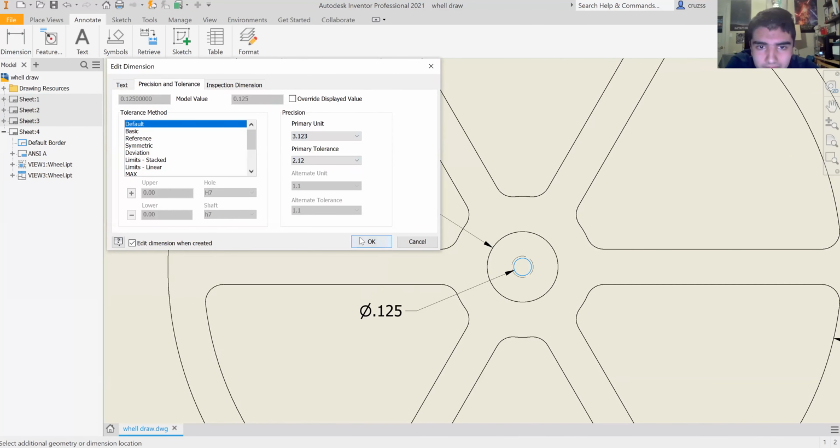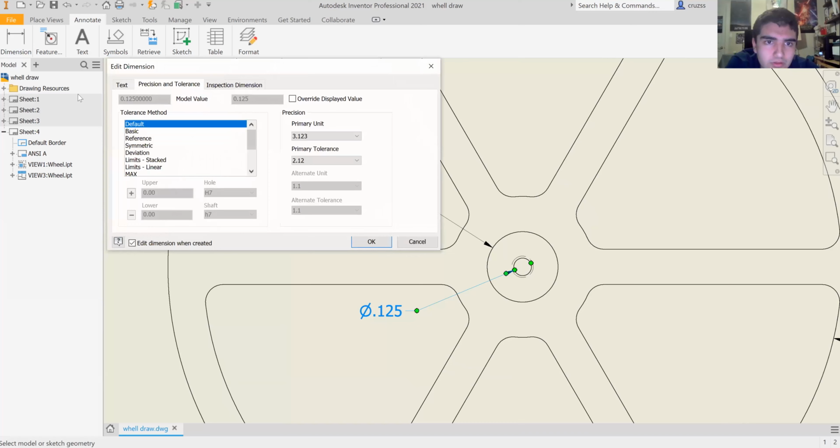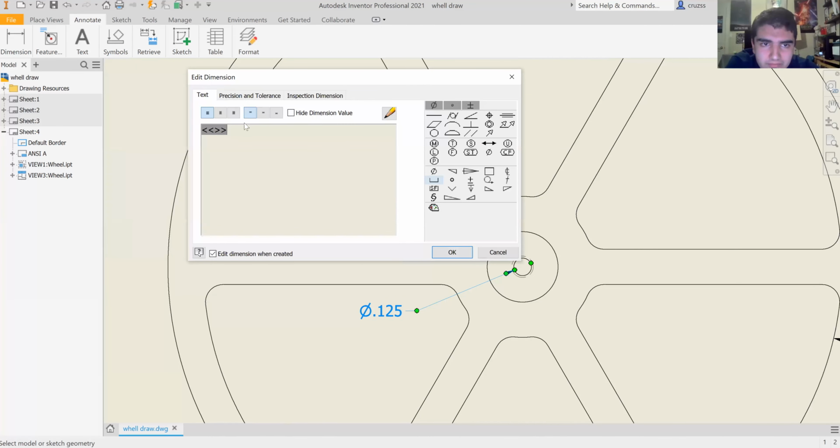And so you're going to get a tap. When this is 3D printed, you're going to get a tap and die kit and make sure that this is fit for a 1/4 bolt to go through it. And so the way we're going to do that is simply by editing this again. So we're going to go here and say, if it'll load, it seems to be stuck right now.